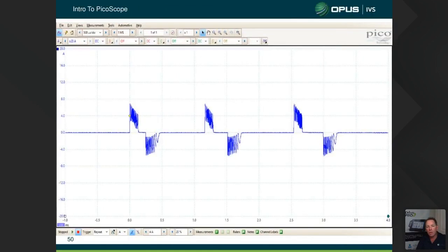All right, so here you can see our current flow in our piezo injector, and it is only drawing about 6 to 8 amps fully open, and then 6 to 8 amps fully closed. Now you can see the current reverses. So we go into the positive current to open the injector, and then that injector is basically held open from here all the way over to here where it closes, right? And all that is the bidirectional drivers inside the ECM just swapping the current flow over.